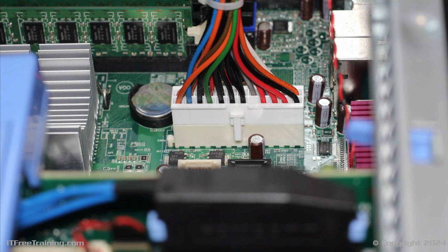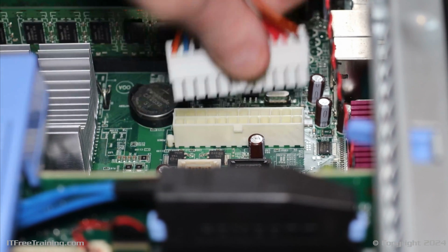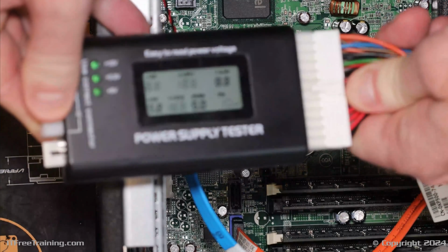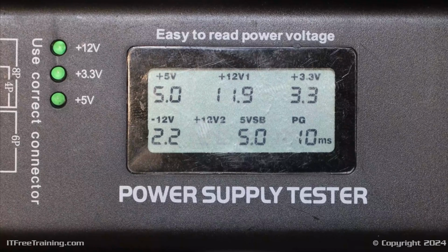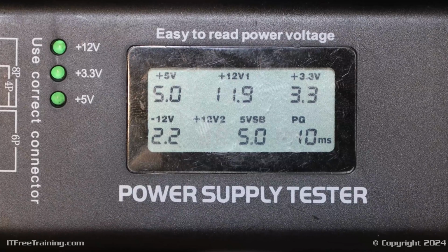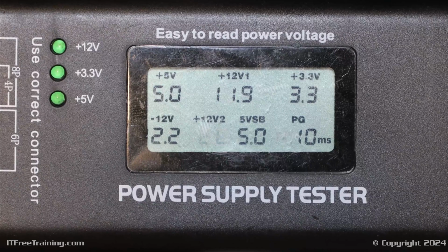I have a different computer to test the power supply tester with. It uses a compatible ATX power supply. I will pull out the P1 connector from the motherboard and plug it into the power supply tester. Power supplies put out a number of different voltages, often referred to as rails. The power supply tester tests the voltages. CompTIA has removed the power supply tester from the exam objectives, but they would like you to know how it works. The voltage can be 5% plus or minus the standard to be considered compliant.